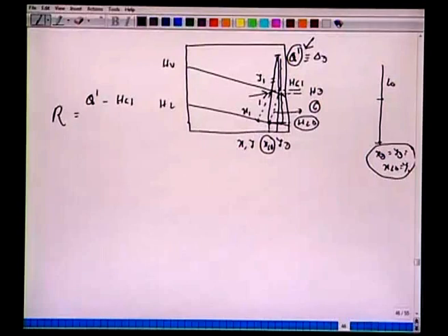Very often we make a mistake here, because in the case of a total condenser we used to take the first segment or operating line here. Here the first operating line starts from stage 1. So, Q prime minus Hg1 over Hg1 minus HL0, which would be this HL0 here. With that, we can construct this HXY diagram for the two scenarios: one was the partial condenser and the second was the total condenser.